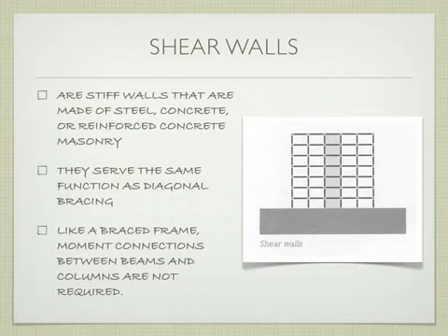If you're thinking about designing a multi-story building, this is a great place to house an elevator, for example, or some kind of building core services, fire escapes, those kinds of things. But it's a solid object broken by very few doors or very small doors, if it's broken at all. That rigid wall panel is then resisting the lateral load. Because we have that solid wall, when you push on it, it's able to transmit the forces. If I'm pushing here, it's going to transmit down through this solid wall toward the ground.